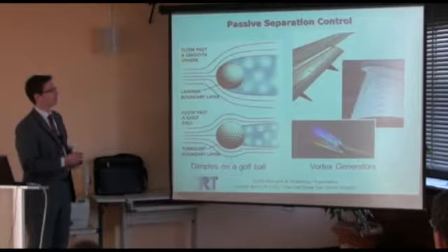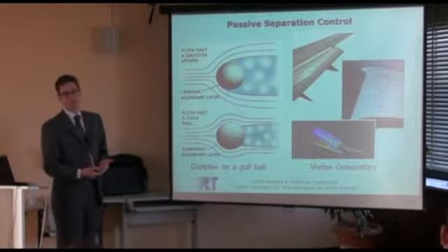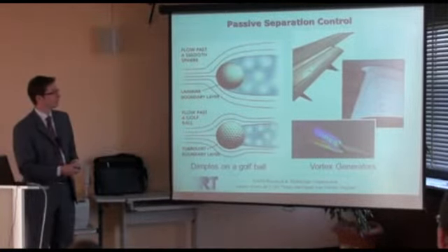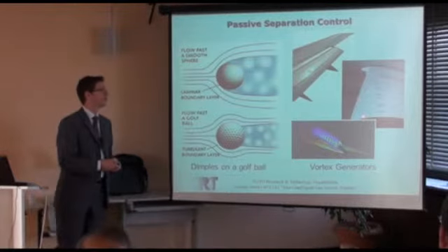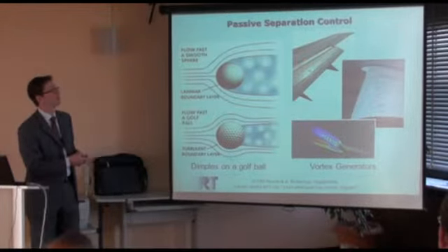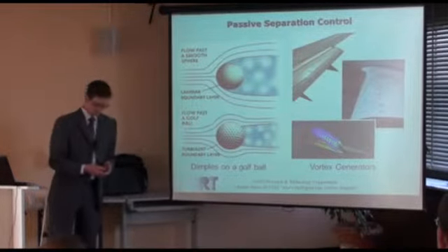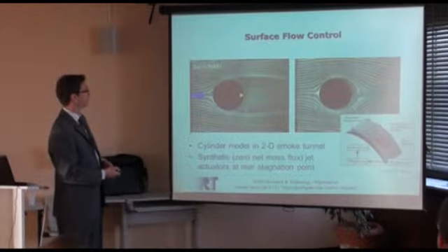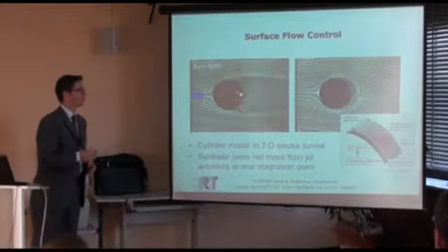So in aerospace there are several means of turning the laminar boundary layer into a turbulent one. Like, for example, these vortex generators here on this wing. There are also some slots maybe where you can induce a certain amount of turbulence. I think that's shown here on the next slide. So that's still the ball here. You see in this experiment the large wake.